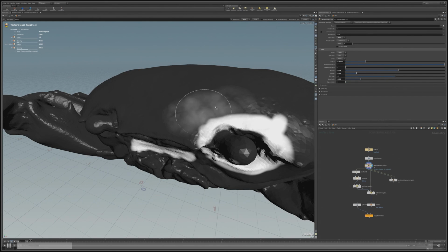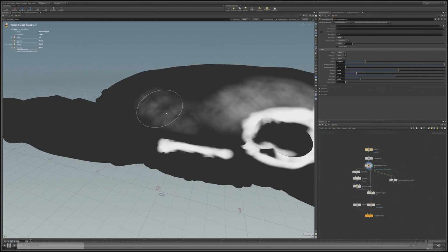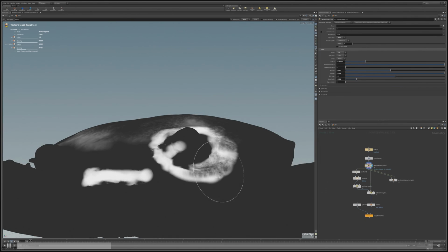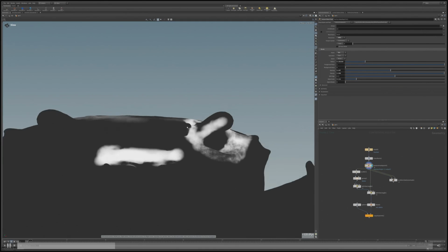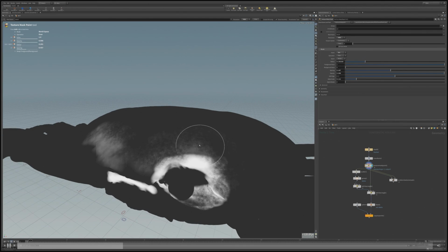The texture data is output as a 2D volume primitive. You can use this primitive as an input for downstream operations or export it to disk as an image file. For example, we can use this volume primitive to derive some simple geometry instancing as we paint.